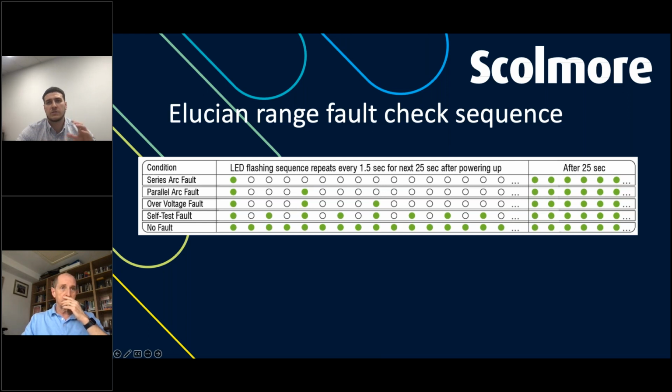So it will tell the microprocessor, okay, I've seen 275 volts now, I need to do something about it and I need to operate. But what it doesn't do is dump the current down to earth. You still need that SPD within the system in order for it to dump it down to earth. So yes, it will tell you if it's gone over that 275 volt threshold, but it won't do anything with the current that's sitting there.